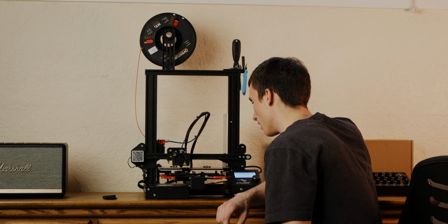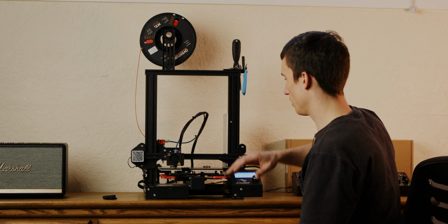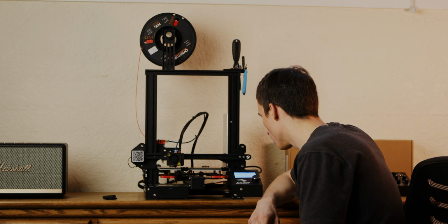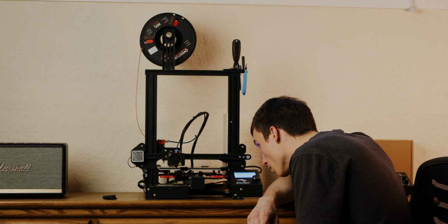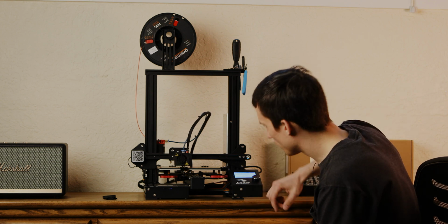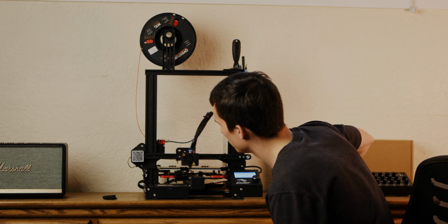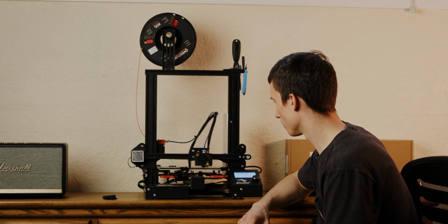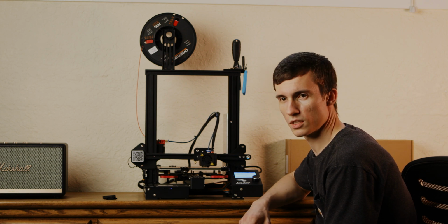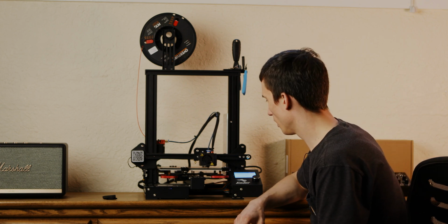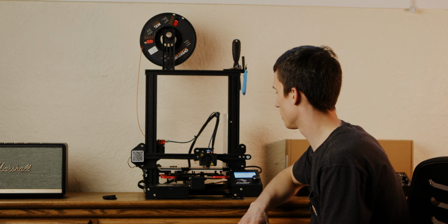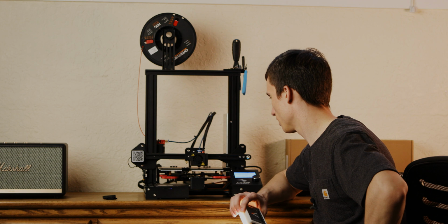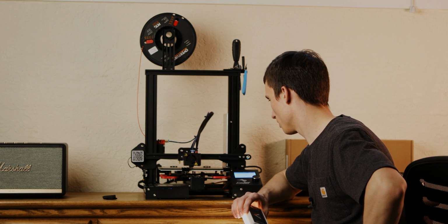Alright, we just had a spot where it didn't extrude for like 2 millimeters. Okay, but hopefully everything evens out and becomes better as it prints here. This brim. But if not, we'll just adjust settings, adjust level, and it could even be that the plastic has been out collecting moisture for a long time, so that could be affecting how it's extruding or how it's able to print with it.